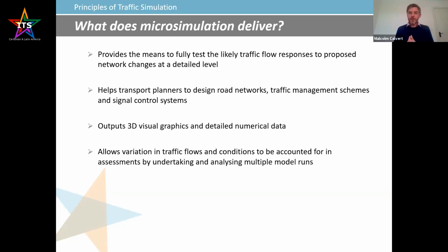You also, of course, get really detailed numerical data out of the model as well, and you can extract that data. And it allows a variation in traffic flows and conditions to be accounted for. So each run of the simulation is just one sample. Our practice is to run these models multiple times so that you get lots of different scenarios run, and you get a real sense of any variation within a particular design.